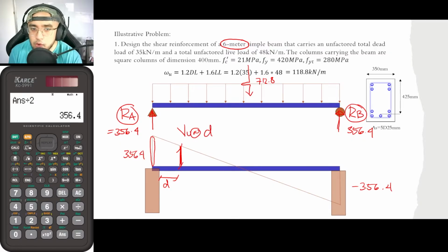So it would be up to you on how you would be solving for this particular shear force here. Either you would be solving for it via ratio and proportion, or you can just make use of the shear equation method. The shear equation method is actually the safest route in solving for your shear, because ratio and proportion is only applicable if and only if you have a linear or a uniformly distributed load. In a situation wherein you would be having, let's say, a triangular load, you cannot make use of ratio and proportion, not in my knowledge.